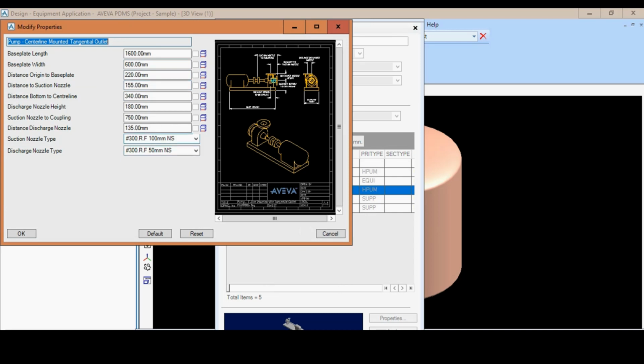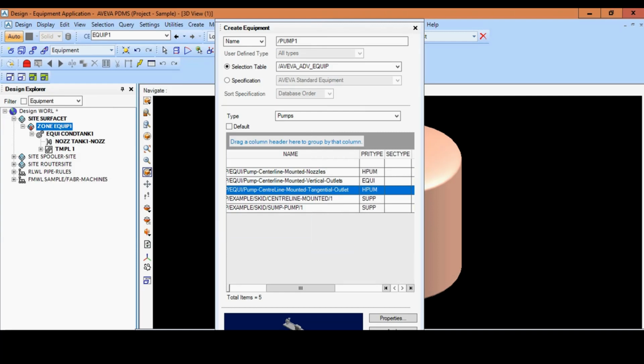So this is also very important because if you want to connect the nozzles from the pump to the tank, you have to make sure that the bores are similar. In order to do that, you can also use reducers anyway, but just to make everything straight, let's select the 100 millimeter bore for both discharge and suction nozzles, and nothing left, just click OK, and it's been created.